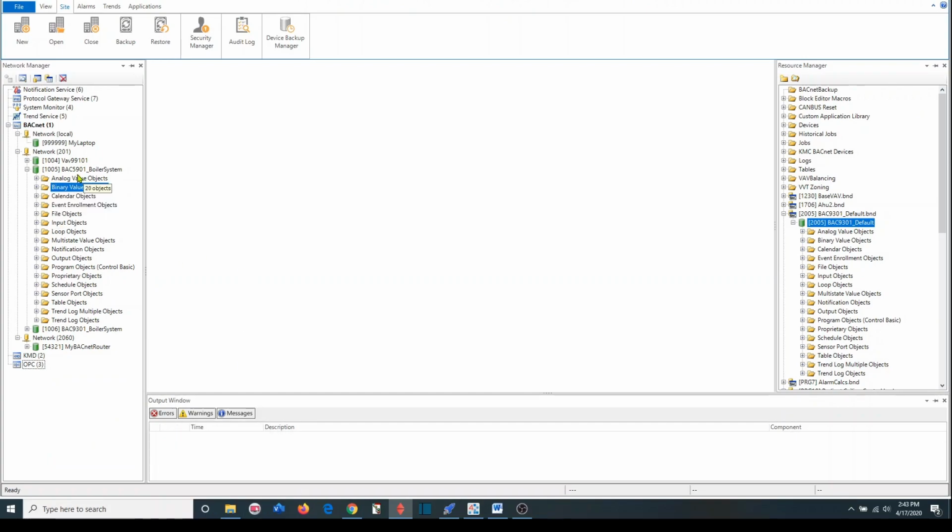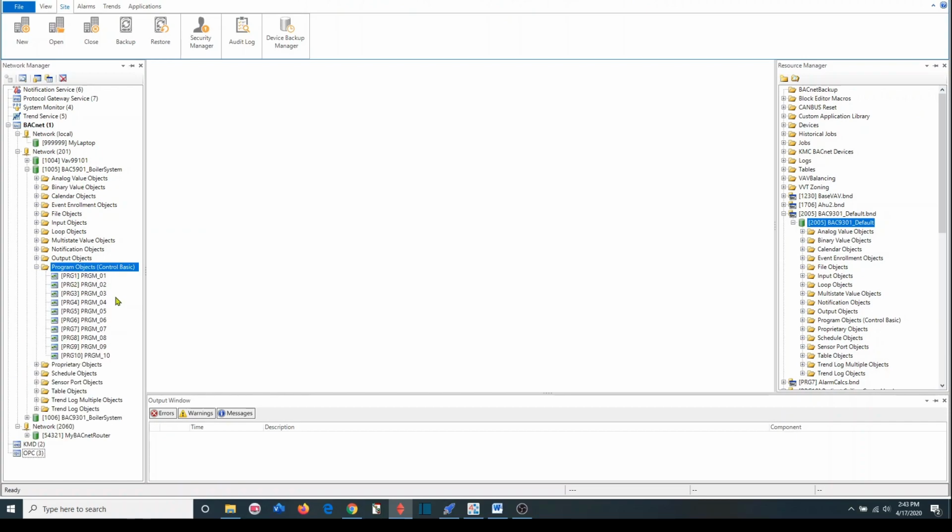On the 5901, they also allow you to add more programs. It defaults to 10 programs, but you can add substantially more. When you're programming with graphical block programming, it's very advantageous and much easier if you modularize your program. So you may be doing twice as many programs when you're doing graphical programming as you would if you were doing line programming.